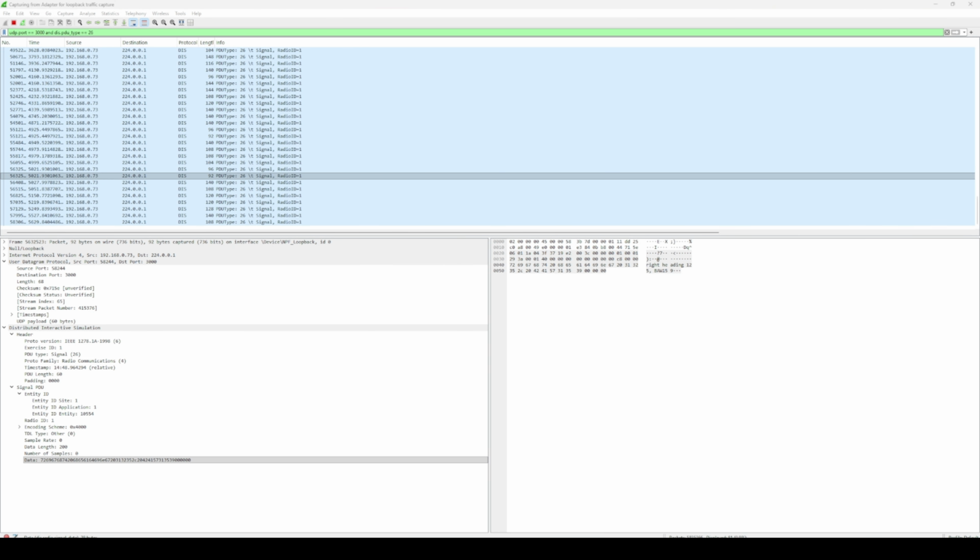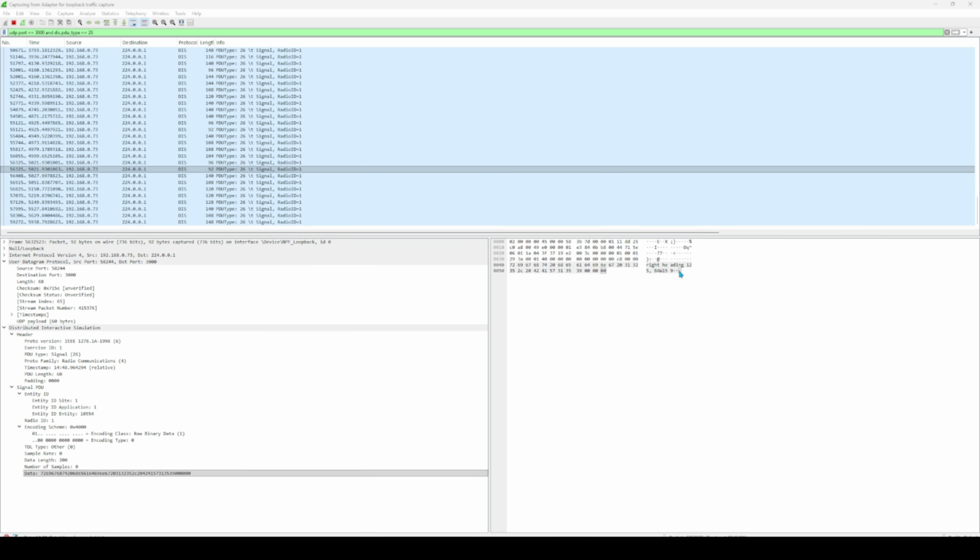Paired with the transmitter is a signal PDU, type 26. Every voice line the sim produces goes out as a raw binary payload, alongside the transmitter announcement. Same radio reference ID so that a receiver can pair them. The transcript is carried as raw binary data, encoding class 1 per the spec. So a federation observer logs the whole voice picture without ever needing a codec.